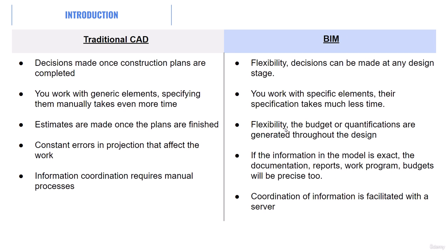So BIM will always try to assist you in specifying as much information as required. Besides this, there's also flexibility with the budget and the quantifications, because if you are modeling something within Revit or ArchiCAD, there are many different options that will allow you to create different quantifications in a matter of seconds. So this is quite an amazing advantage that we get with BIM. At the same time you're already modeling the project, you can generate a quantification at any stage of the design. The difference with traditional CAD is that usually this process takes place once the plans are finished, but